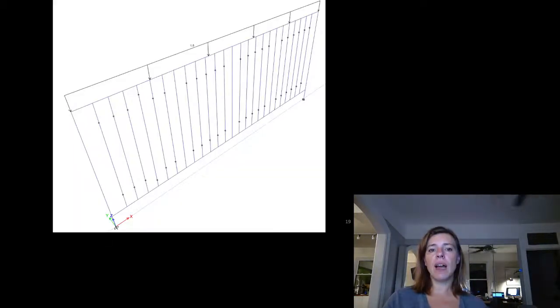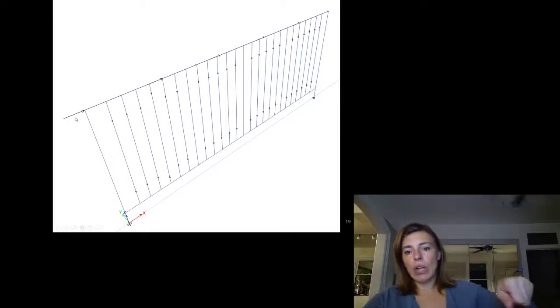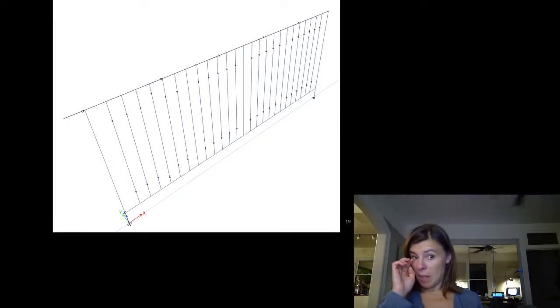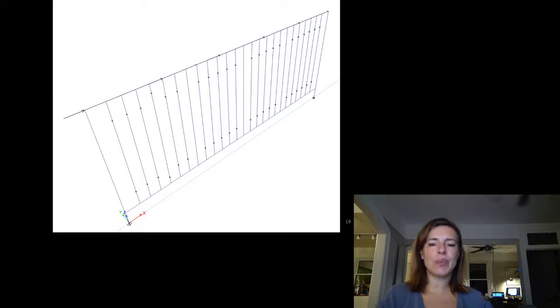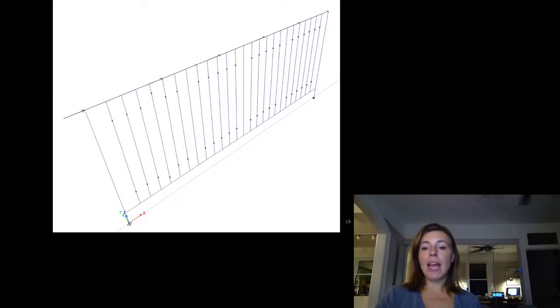So let's take a look at the live load cases I modeled. There's the 1.5 kilonewtons per meter downward. I did 1 kilonewton along its length because the code does say it needs to act in multiple directions. But it actually doesn't explicitly say that. It's loosely alluded to, and the handrail code very much does.